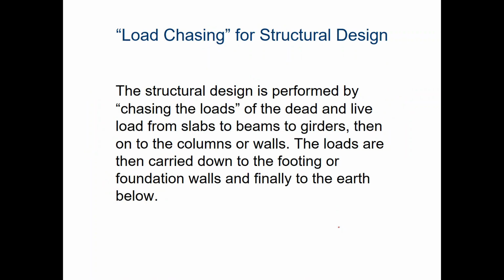This is a nice definition here. I like it. It encompasses the whole load chasing pretty well. So the structural design is performed by chasing the loads of the dead and live load from slab to beam to girder, then onto the columns or walls. The loads are then carried down to the footing or foundation walls, and finally to the earth below.